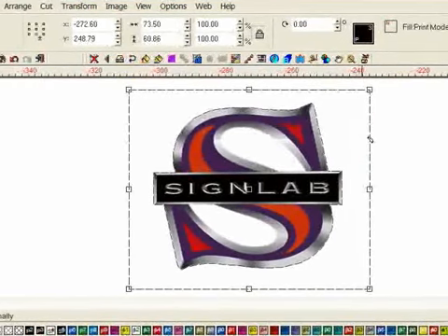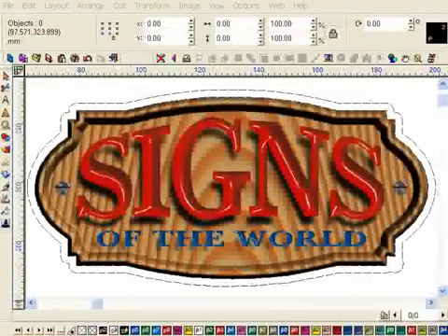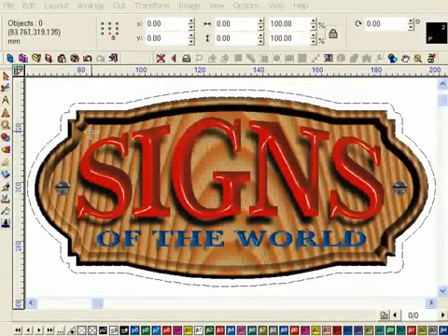Remember here that if you create your half-cut paths in this way, and they are to be produced on a machine that recognizes them by color, you would need to select the required color from your palette. Okay, so let's now return and output my original example. I will be using the Roland VersaCAM and the variable pressure method.